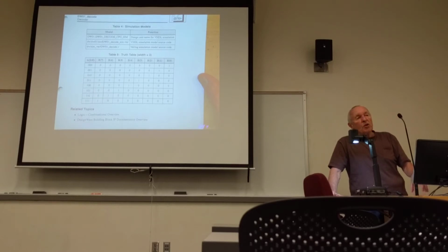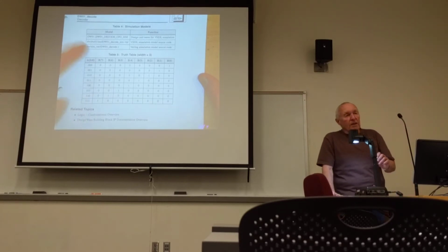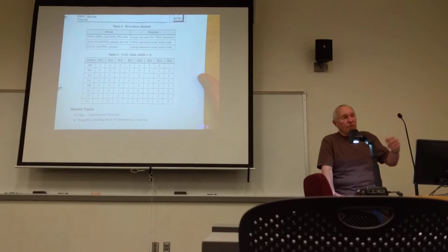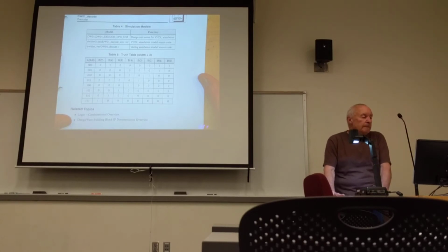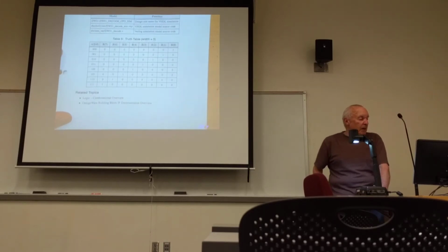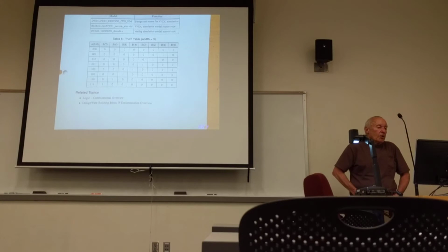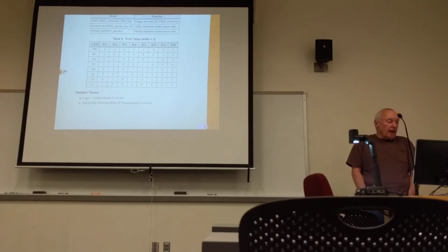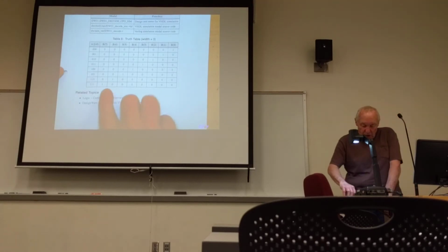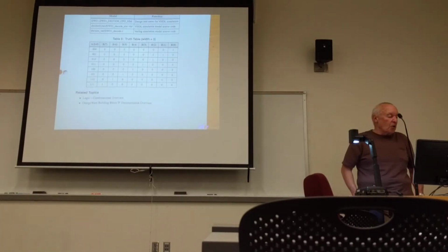When you are going to use this in your design, you have to use the actual Verilog source code module, not the simulation file. They just did this so that it's efficient to simulate and will improve the turnaround time for your simulator. So they give you an example here of what you can expect. In this case, I've got a width of 3, so I've got 8 outputs, and you'll notice that the way this is set up, the asserted output is always a logic 1, and all of the rest of the outputs are a logic 0.